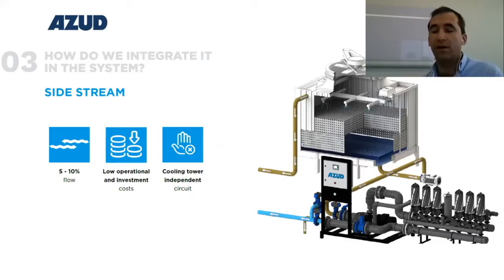Also, you have a reduction in chemical use. Chemicals are used to bind suspended solids in the water stream and prevent scaling and corrosion. Dirty water requires more chemicals than clean water because the buildup of solid contaminants provides a buffer that reduces the effect of the chemical treatment. A side stream filtration can remove suspended particles and reduce the need for any additional chemical treatment, such as dispersants or biocides.